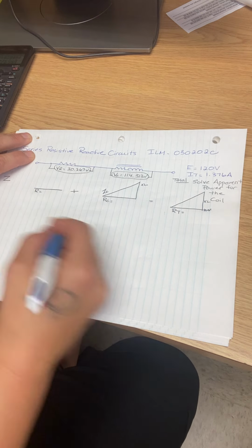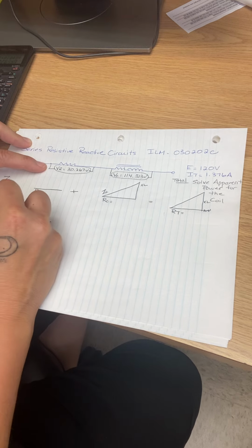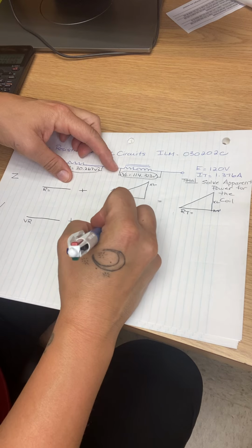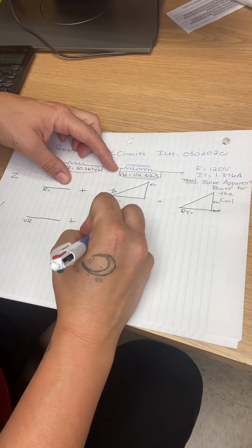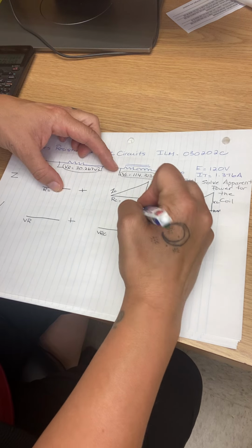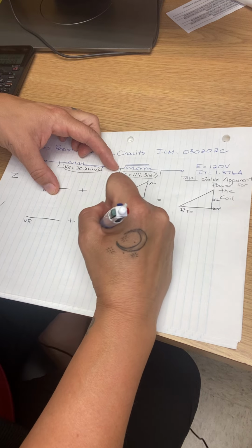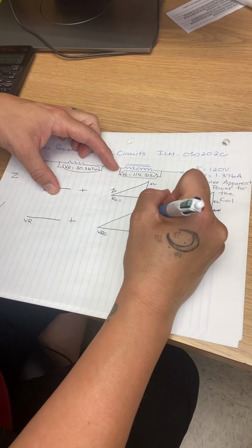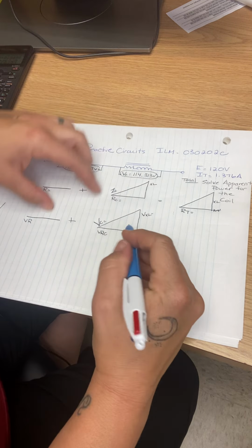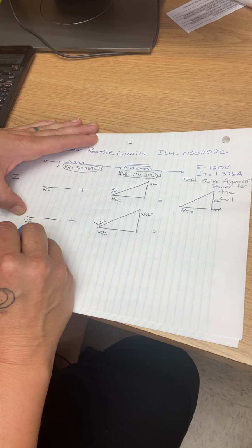Okay, and so then the voltage triangles for this circuit would look like this. The volt drop across the resistor would be an in-phase volt drop, so VR, plus the volt drop across the resistive portion of the coil, my VR coil, an in-phase volt drop, that's vectorially added to the volt drop across the VXL. Then I would add them together vectorially, meaning using Pythagorean, and that would give me my volt drop across the coil.